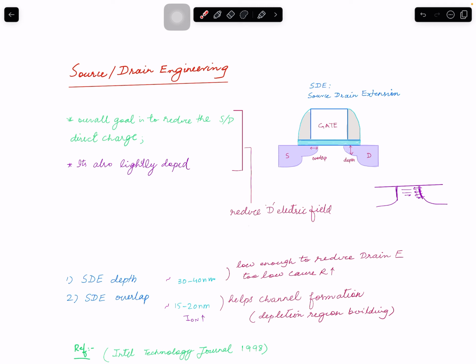So two things were done here, one I already mentioned. I believe this one I didn't say. Not only do we make this extension, this is called source drain extension. It's made on both sides equally, in a similar way. It's called SDE. This area is also made lightly doped. I mean, this is N plus, right? N plus means electrons are the majority carrier. Pure silicon, electrons were not mobile, so in order to make it more conductive, we added impurities, and the result of impurities is that we have more electrons. So you put fewer impurities here compared to here. And that's why we had these spacers, in order to grow this area until here. So this shape plus lightly doped.